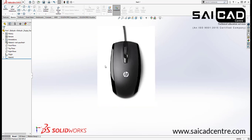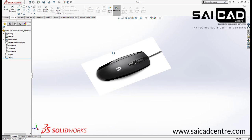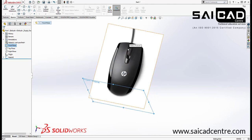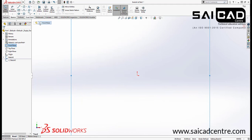Now if you have a different view also, you can insert that view also. I have a front view for this object. If you see here in the front view, our object is in a different side. If I place the front view here, this object is in a different side. So right now I'm just going to insert the view first. Go to the sketch and insert an image directly from here, and I'm going to use the front view from here.